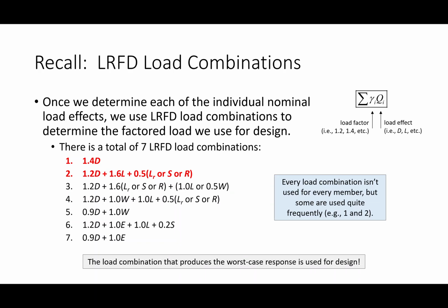Let me ask this. Does it look like this? So you've got a steel beam. Yeah, so you've got these like little nail things that are sticking up on top of the beam. Y'all know what I'm talking about? Have you seen these? Okay. Why are those there? Hold the concrete in place? Exactly. So as you place the deck, the concrete interlocks with those studs, and it makes the beam what we call composite, okay?